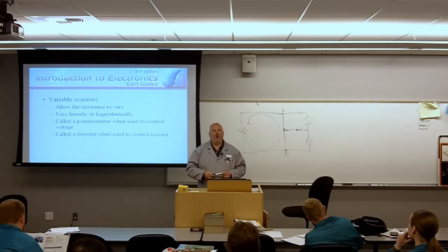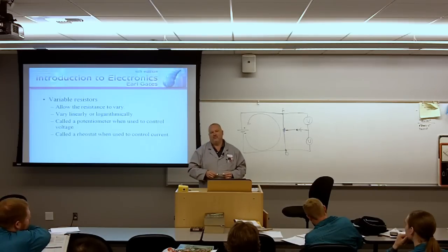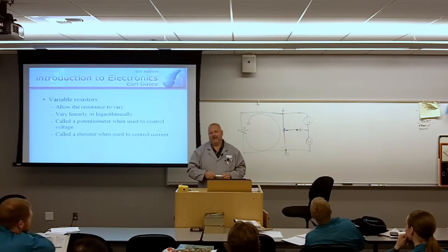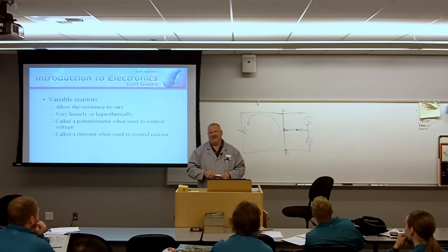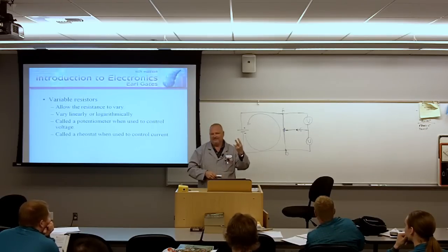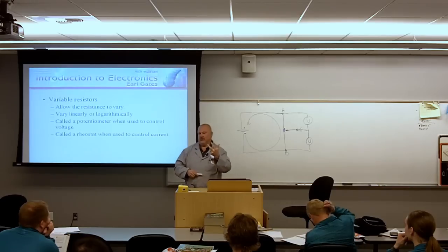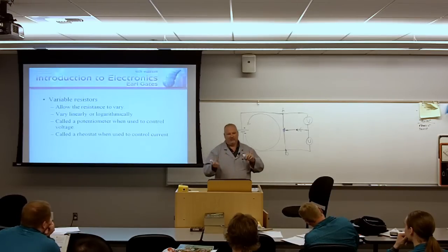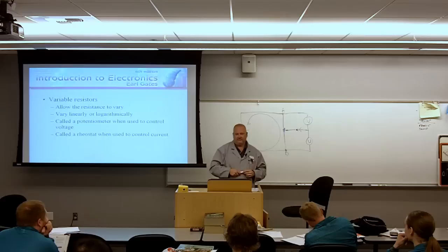If you went out and special ordered a rheostat, and it came in the box and it said rheostat, could you use a rheostat as a potentiometer if it only came with 2 terminals? No. You need that 3rd terminal to be able to divide the voltage. Make sense?